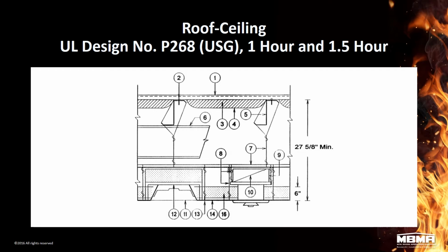Here is the other USG counterpart to the Armstrong ceiling assembly, P268. It's rated for both 1 hour and 1.5 hours, and in general it's pretty similar in terms of the construction. Just the acoustical ceiling system and the allowances are particular to the USG system.